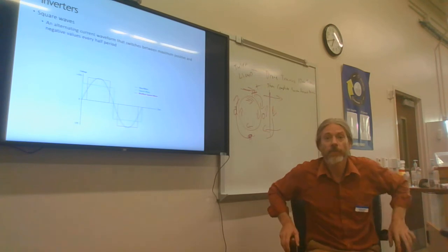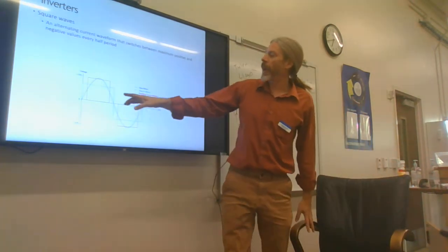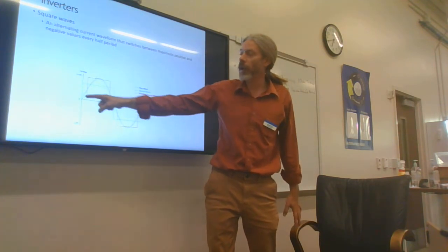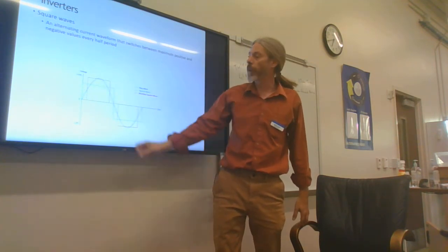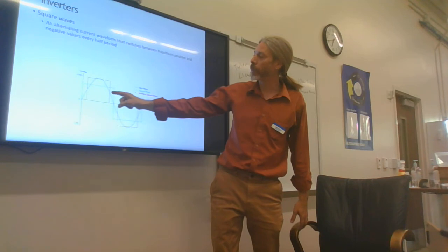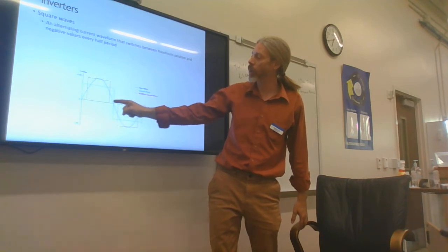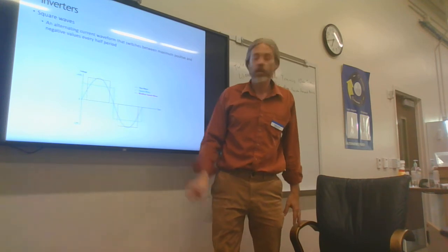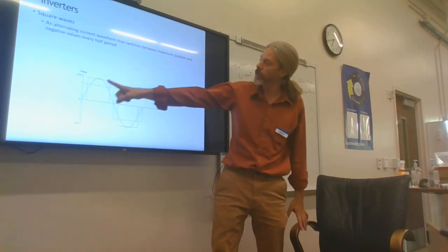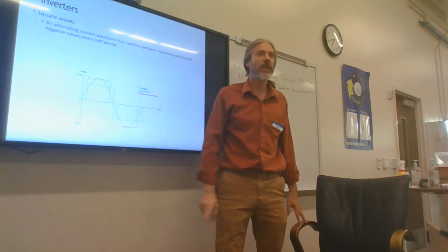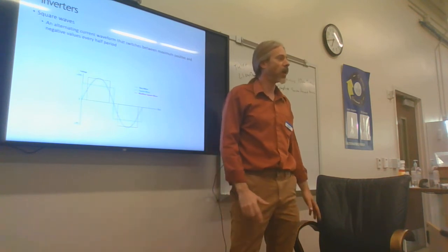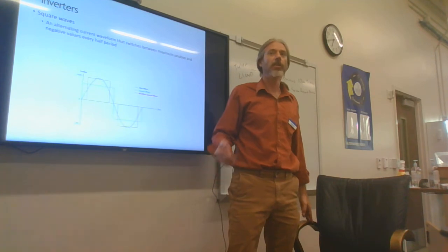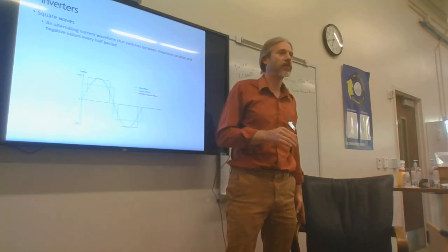to this. So apparent power would be all of the space underneath the green box. True power would only be the part of the green box that is also within the blue area. This area here is wasted. This area here is wasted. All right. It's why the closer to a sine wave signal that we can create, the more efficient the inverter will